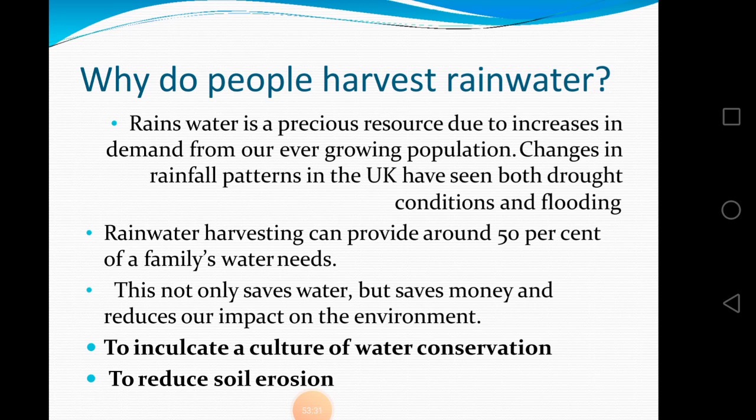So as far as rainwater harvesting structures, especially for recharge, are concerned, it depends upon the area and location. We can have various structures: storage of rainwater on a surface for future use, that is rainwater harvesting, recharge to groundwater through pits and trenches, dug wells, hand pumps as we discussed, and recharge shafts and lateral shafts with the bore wells as we discussed.